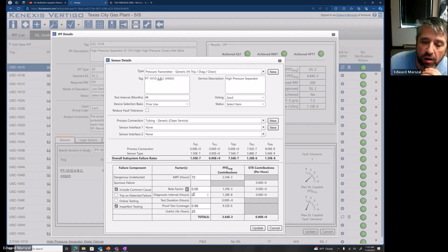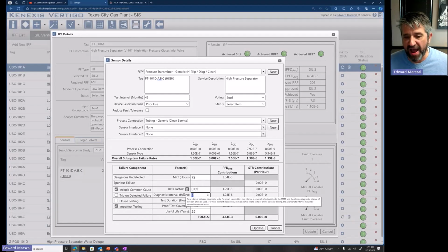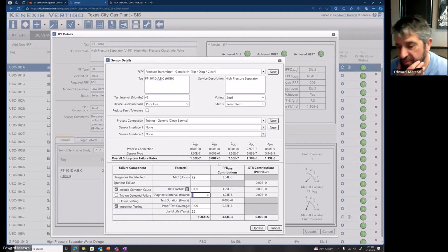So if it is a 2 out of 3, it is looking at the fault tolerance. Yeah, so this number is for one component, and the fact that you have redundancy, all of that is in the terms of the calculation. Yeah. No, because I was surprised that for this configuration, let's say, I put 1 year, so 8,760 hours, and it was like 10 to the minus 5. So I said, wow, I was not expecting it being so nice.